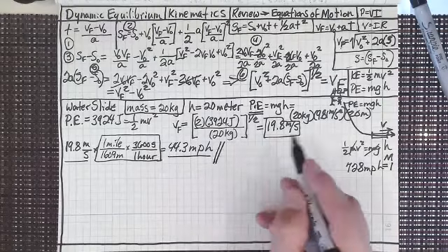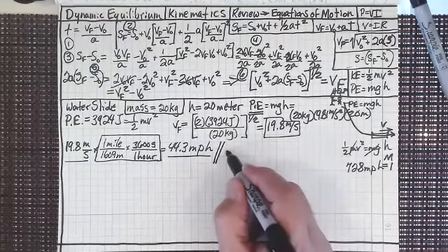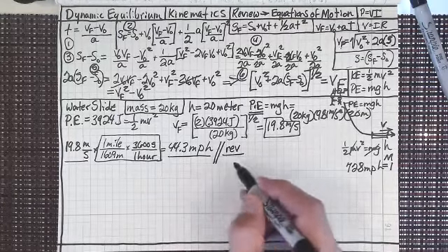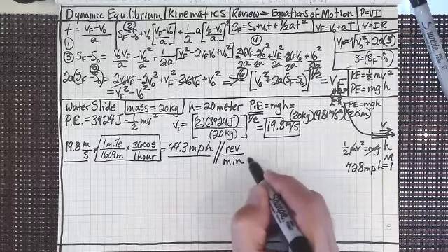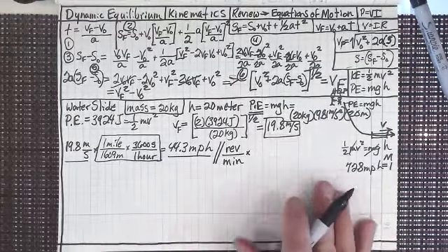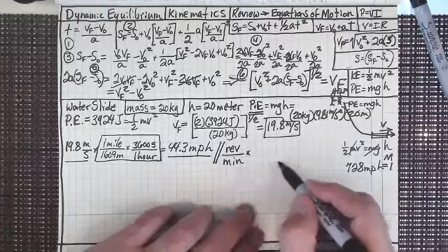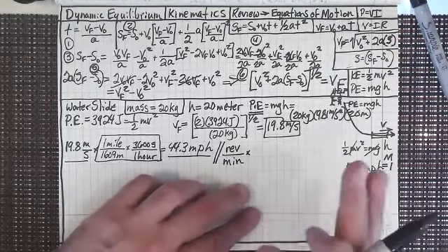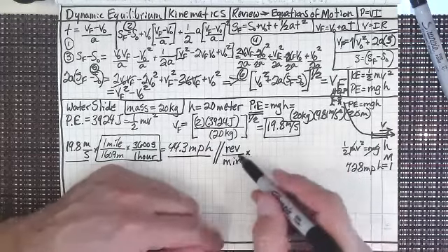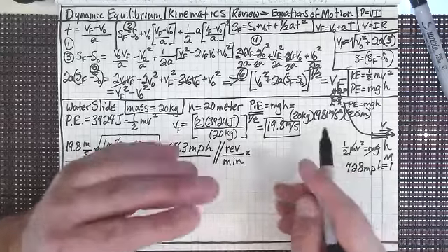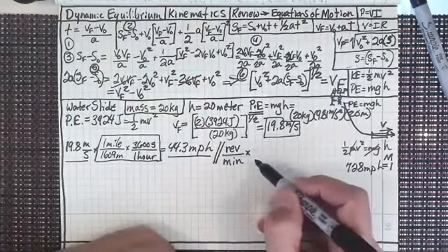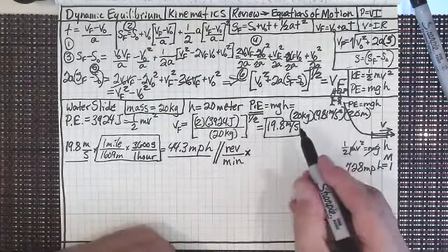Now, let's move on, because I want to change RPM. What is RPM? RPM is revolutions per minute. Now you're going to be doing a lot of things that deal with RPM. Even in this dynamics course, we're going to be working with revolutions per minute. When you get into motors and controls, you're going to be working with revolutions per minute. And you're going to want to turn that into radians per second, because engineers cannot use revolutions. They can't use degrees. They've got to use radians. That's the only engineering unit that we can use.